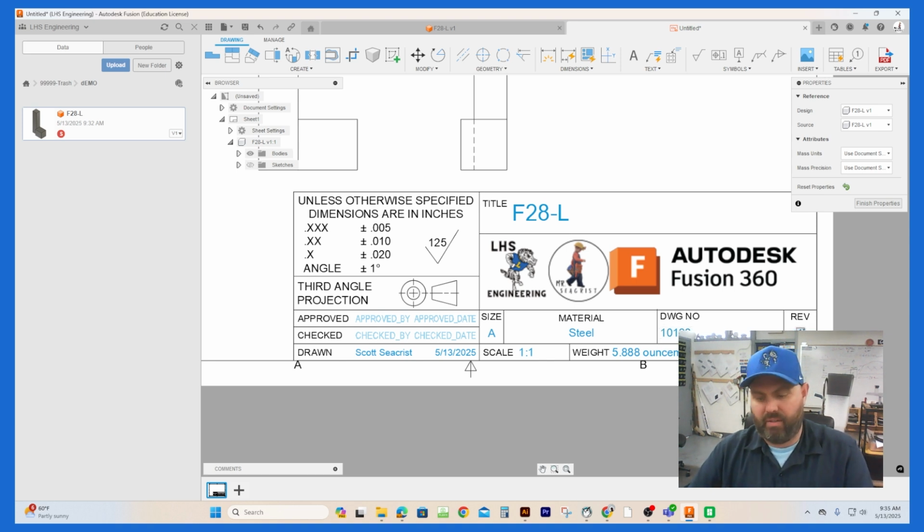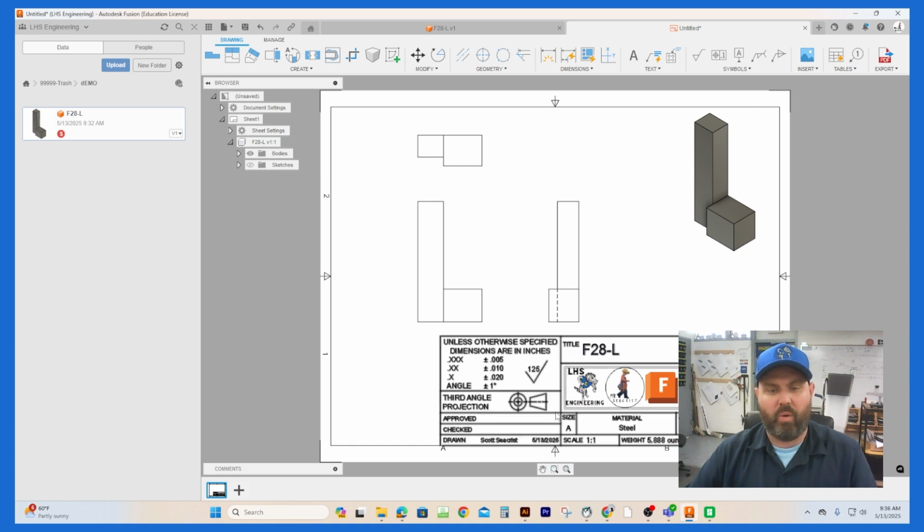We're going to go ahead and click on Rev and change Rev to 1 because this is the first revision of this design. Every time we change it, this number goes up by 1. And then don't forget to hit Enter, and then go ahead and hit Finish Properties. We now have the basics of the drawing document laid out. Let's save it before we forget to, so go ahead and hit Save.